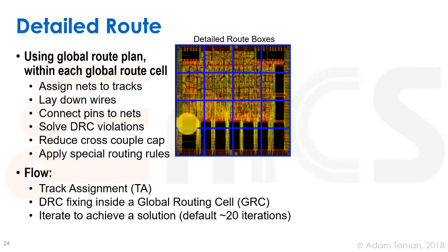So once we finished our global routing, we can start detailed routing. What we're going to do is we're going to take each of our G boxes or our G cells, and we're going to do track assignment, saying each net that's inside, where it connects to the next G box. We're going to give it a certain track that it has to meet, and then we'll set the source and target for each of these nets, and then we can go and do this detailed route, which is a more fine-tuned grid routing that actually takes each and every single one of these layers and connects it from the source to the target in a detailed way inside the grid box, inside the G box. But it's a much easier problem than routing the whole design.